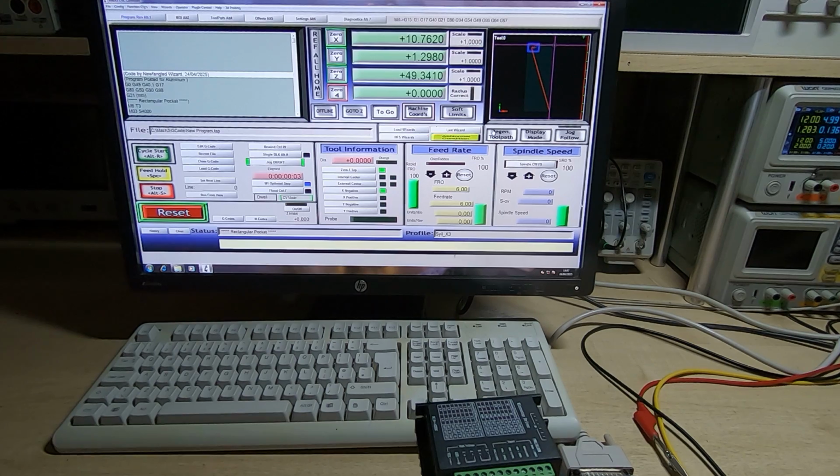And if we regenerate the toolpath, if I zero X, Y and Z, so we've moved the tip of the tool that's currently in the machine to a suitable starting point based on the stock that we put into the machine. If we regenerate the toolpath, you'll see that it's generated this toolpath referenced to the center point of the material or the milling operation, which is what I told the software to do when I generated this file.